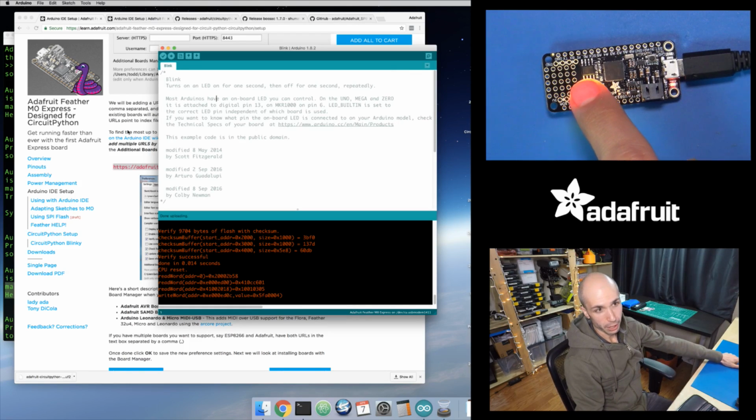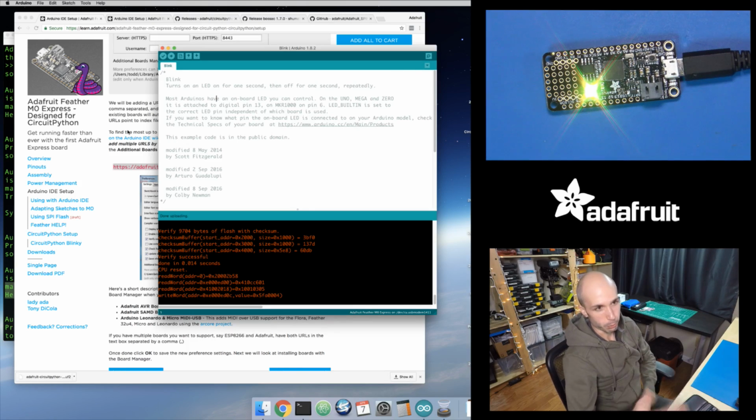All of that is still on the flash chip, because when you reprogram this board in Arduino, it's only reprogramming the SAMD21 microprocessor. It's not going to touch your flash chip unless you run some code that talks to the flash chip and reprograms it. So that's a cool, handy feature, in that as long as you don't mess with that flash chip, you can still access the contents of it from Arduino.